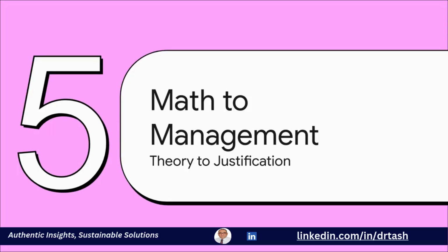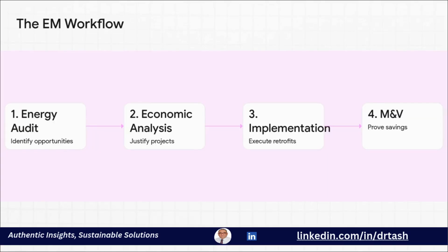Okay, for our final section, let's bring it all home. We've gone through a lot of math, but let's be clear, this isn't just some academic exercise. These are the tools we use to drive the real work, day in and day out. Just think about our workflow. During an audit, you're using the thermal load and performance equations to find opportunities. When you're building the business case for a VSD, you're whipping out the Affinity Laws to quantify that ROI. And at the end, for M&V, you're using those exact same equations to prove you delivered the savings. Every single step is built on this mathematical foundation.